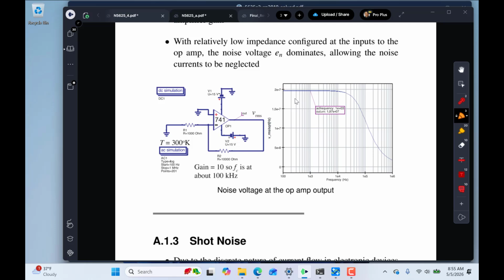What I ended up doing in this project was I replaced the low-cost op amp with a low-noise op amp to try to reduce the amount of noise coming out of the op amp that was introducing phase jitter or phase noise in the synthesized output. That was a nice thing to do because I was suspicious that that was the problem. But in the very end, I'm just telling you what I ran into, and this is a typical engineering scenario. You go chasing after things, saying, I bet this could be a factor. So I redesigned it, and a low-noise op amp was a good choice for a low phase noise synthesizer.